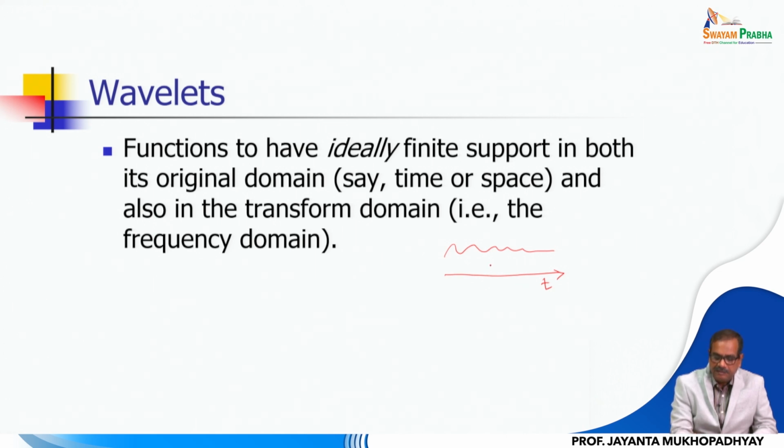Now, when we are transforming this signal, we may consider the whole interval of the signal, if it is a finite signal in a discrete domain, and apply the signal transforms here, for example the Fourier transform. You may get some kind of Fourier response. Say this is the magnitude, and suppose this is the phase of the signal. Now, this is the Fourier transform representation.